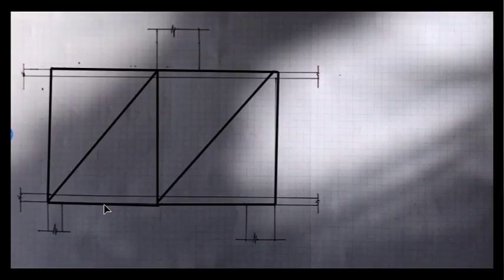This isn't just for transfers, this is for all wall designs and all columns. Before you start the design, think about the crane capacity that the builder can get onto the job and think about what can be carried in the truck to site. That's if they're going down the precast route. Right here I've shown a precast panel breakup. This might have been because the crane cannot carry the whole panel, so we had to break it up into two.